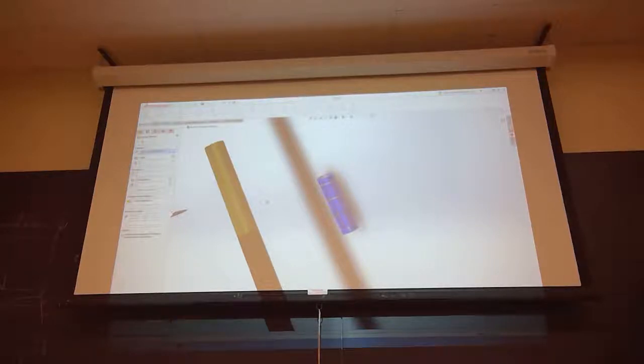But what if you wanted to do it just like this? You have to do 2 steps. Actually, there might be a janky way to do it, some obscure function. I don't know everything about SolidWorks, but if I had to do that, I would just do 2 patterns, because if you want them independent anyway, chances are you don't need them to be the same distance. So you actually do want them as separate patterns, so you can adjust them independently.